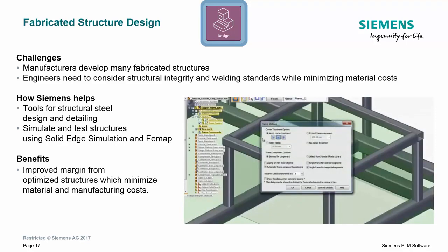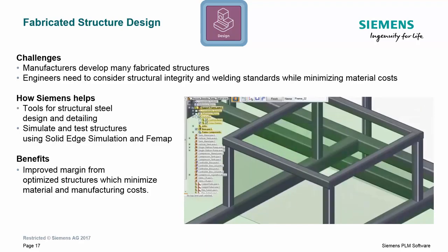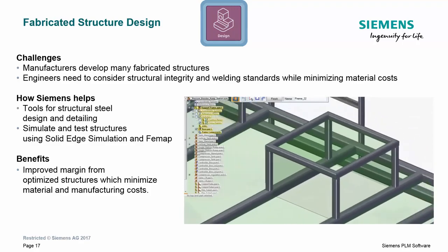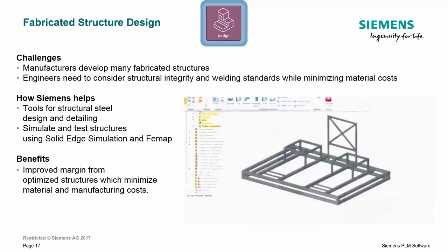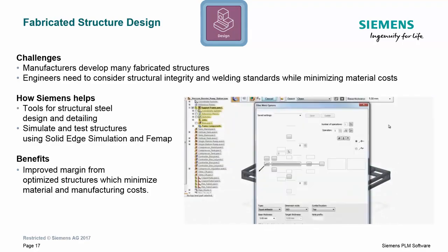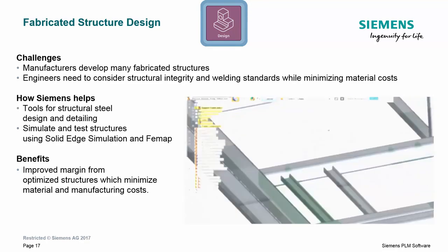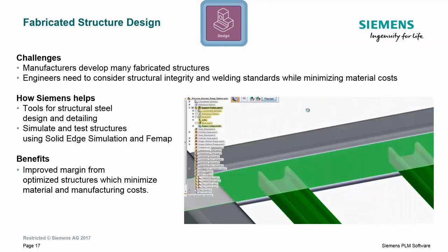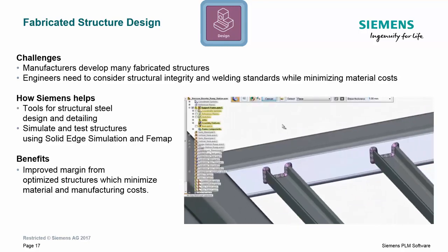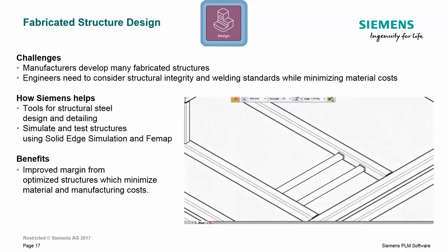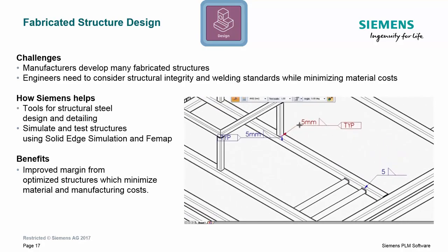And with universal and individual end condition settings, Solid Edge easily manages corner and connect conditions, with full control of miters and coping in a simple, one-click process. And as a framework is built, welds are needed to hold them together. Solid Edge offers a complete toolset for weld bead creation. This includes every type of common weld, as well as custom welds and annotations for use in manufacturing drawings.